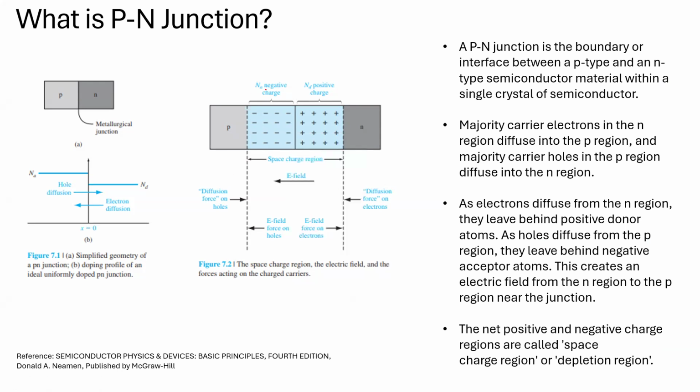So in the figure, this is called the space charge region, which is mainly the result of majority carrier diffusion from the P and N types, respectively, leaving charged ions. There exists an electric field in the space charge region which directs from the N side to the P side. So this space charge region is basically responsible for the directional property of a P-N junction.